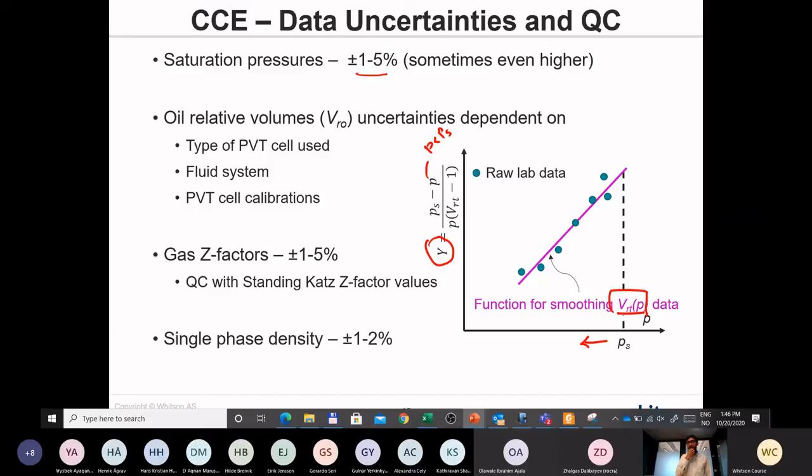But when you say some gas volume will be lost, what do you mean by that? Because we are not removing anything from the PVT cell here. Of course, there will be inaccuracies in the volumes that you measured. If there are any inaccuracies in the total volume, that's what we are correcting for here.